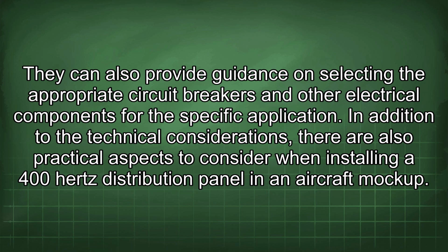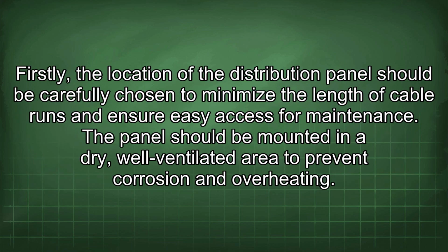In addition to the technical considerations, there are also practical aspects to consider when installing a 400 Hz distribution panel in an aircraft mock-up. Firstly, the location of the distribution panel should be carefully chosen to minimize the length of cable runs and ensure easy access for maintenance. The panel should be mounted in a dry, well-ventilated area to prevent corrosion and overheating.